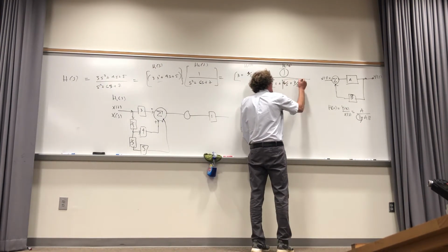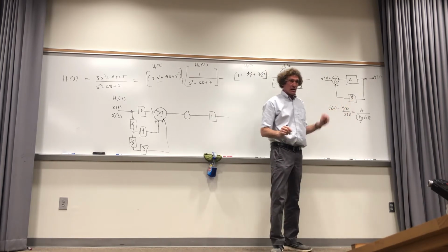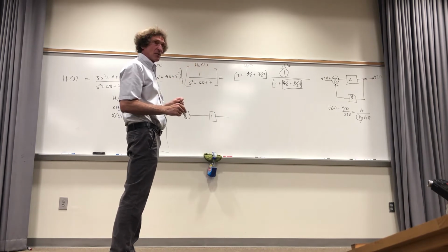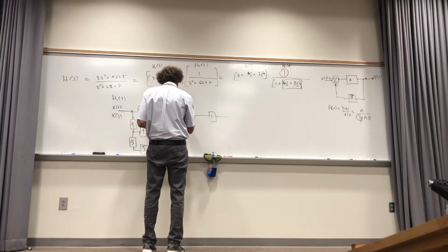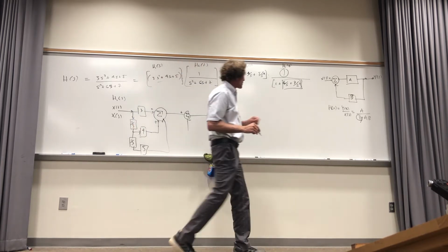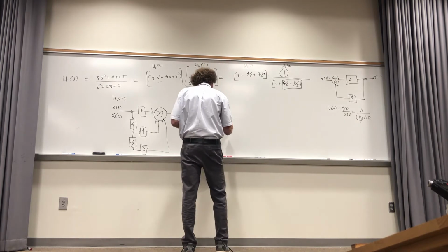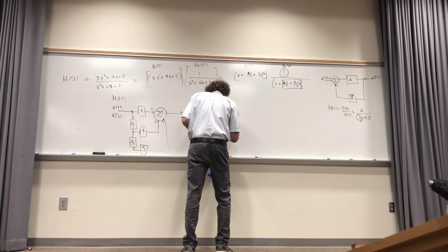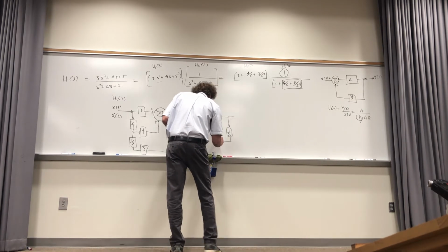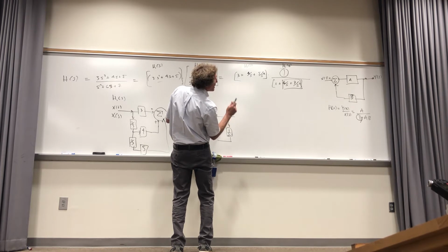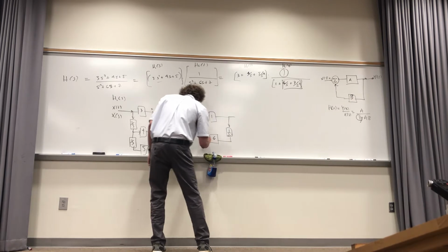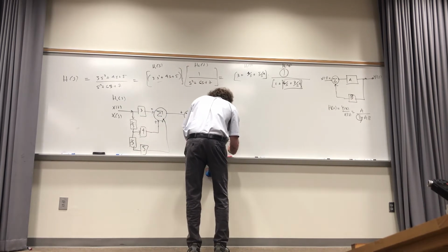Now what happens? This is what? That's E, isn't it, class? Y'all see that? That's going to be the negative feedback going back here. So this is the plus. This is the summer right there, and that's negative. Now the first term is a 6 over s, right? So now I come from here and I bring a 1 over s block, right? And then I take the output of that and feed it back through a 6, the value 6, and then that comes back, it's a negative feedback. Then I need another 1 over s block, right?